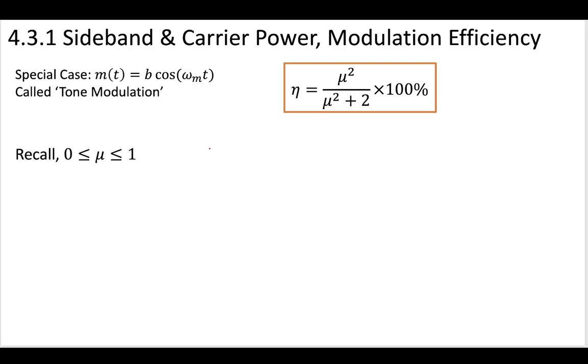And this was what was seen in those previous videos in chapter 4.3, the introduction video. So we needed this modulation index to be between 0 and 1. And if you recall, we said that if the modulation index is exactly 1, that was basically the bare minimum. And then a larger mu means a smaller A. So if you make this mu larger, push it this way, that means that your amplitude A, the carrier amplitude coefficient, is smaller.